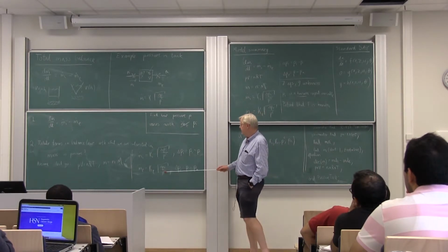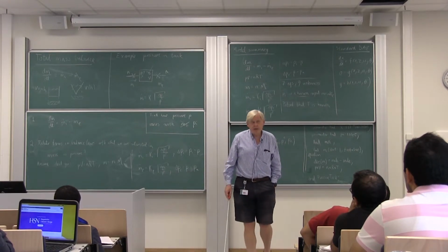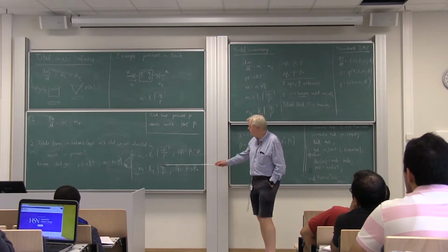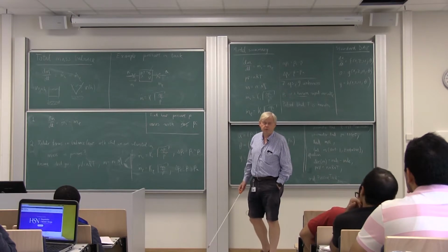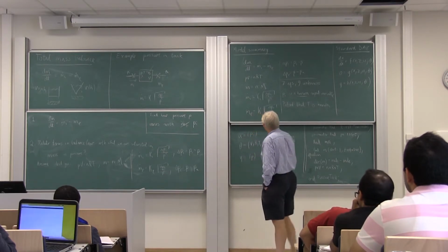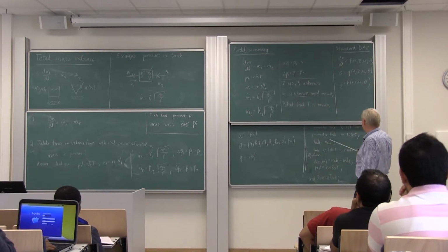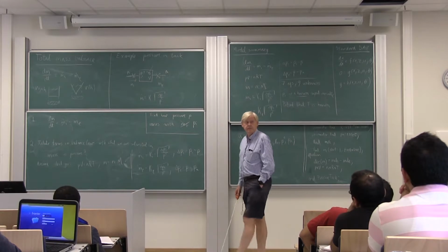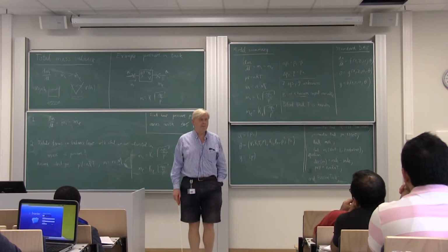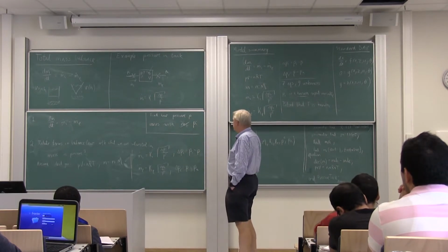But to set the scaling pressure equal to ambient pressure is probably a good idea, because then you get the value inside here to be somewhere between 0 and 1. So if you want to choose this scaling pressure, I would probably say that parameter real PS equals PA. Okay? That was one comment or question.